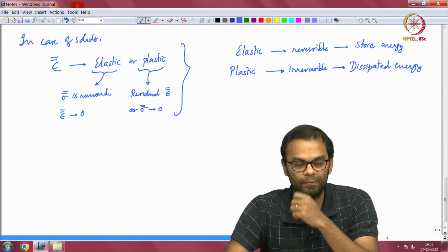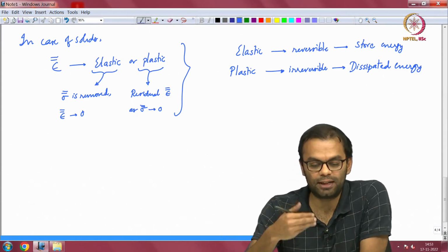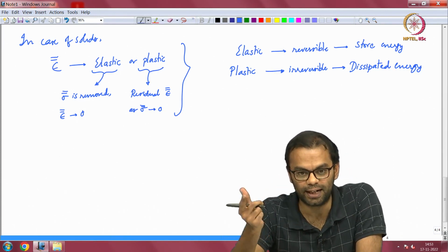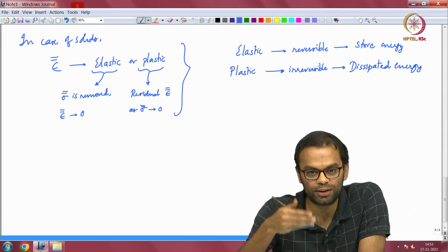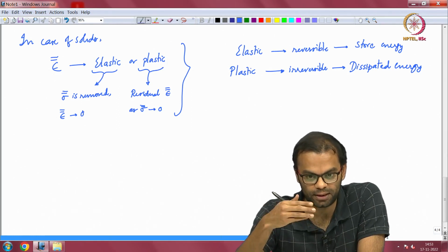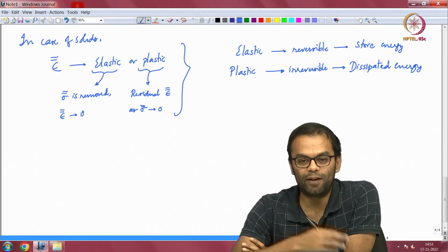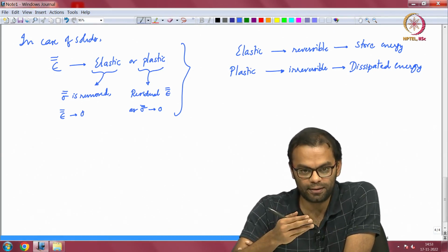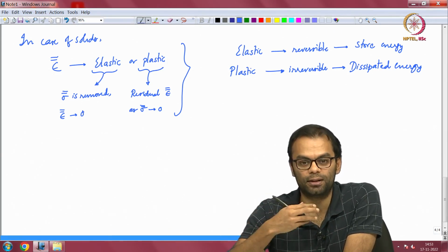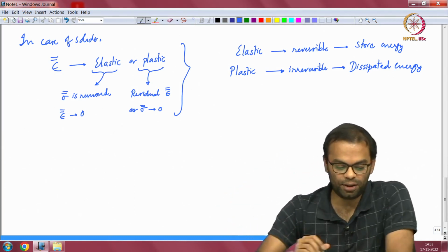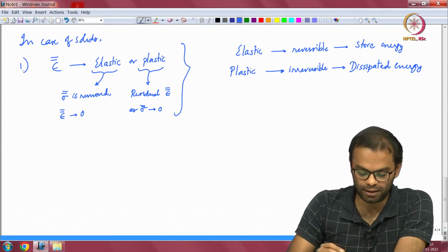Okay. So, this distinction has to be made. There are some techniques, for instance photoelasticity, that we talk about, that has the word elastic in the title, right. So, you cannot use it directly for situations where the strains are plastic, where you have gone beyond the yield limit, for instance. So, you have to be a little careful about the nature of the deformation, where it is coming from, whether it is reversible, irreversible and so on. But in addition to this, so this is the first complication.